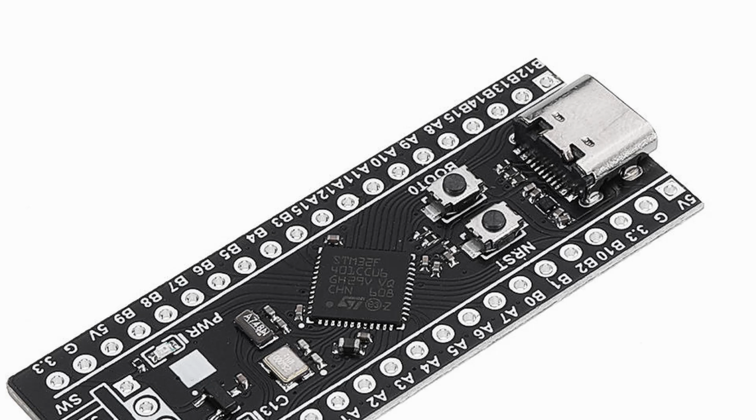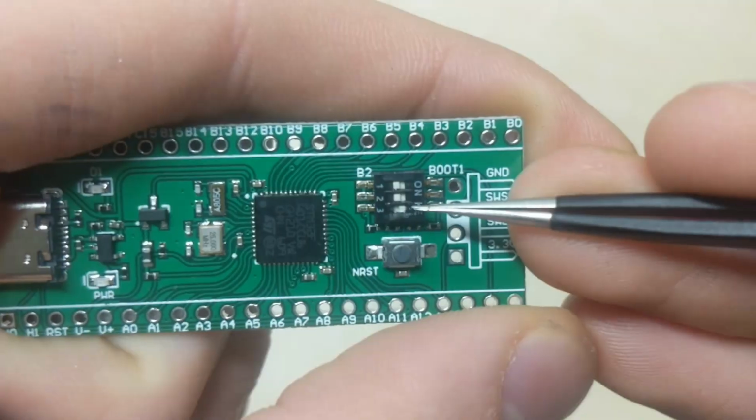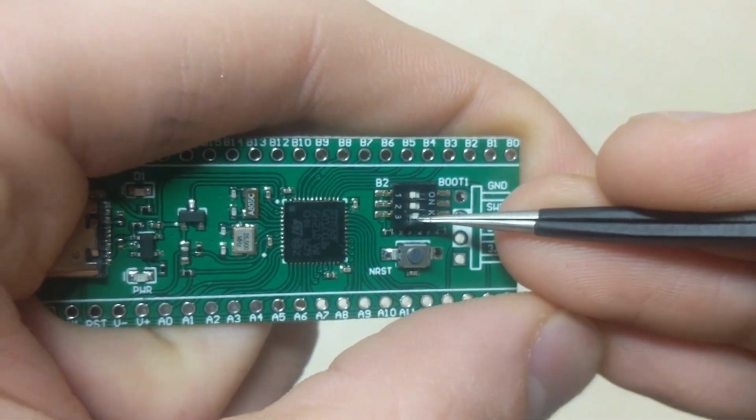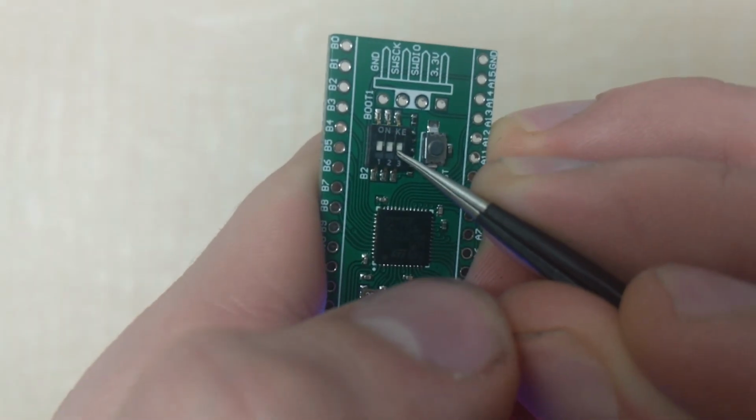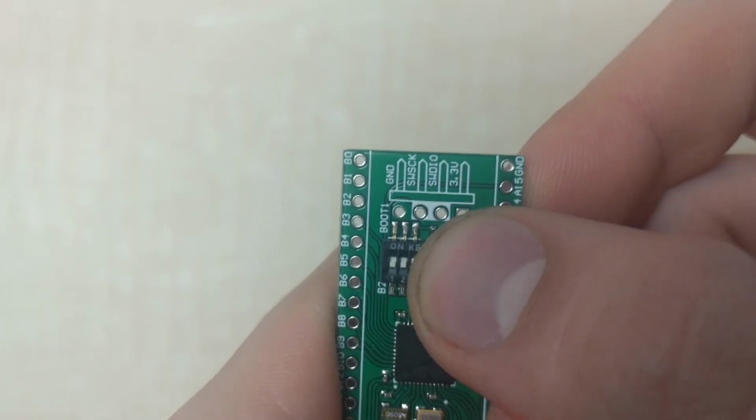From now on, you can upload code by repeating the process of pressing boot 0 and reset, and then pressing upload in the IDE. If you have dip switches like me, you can leave boot 0 on and just press reset. If you have dip switches and want your code to run when power is applied, however, you must move the boot 0 dip to off. You will need to move it back to on and press reset to upload code again though, so while testing you can just leave it on.